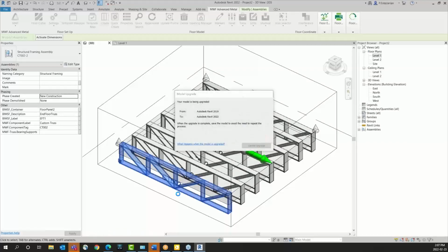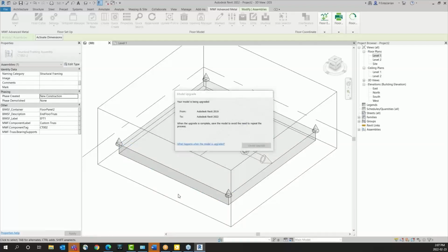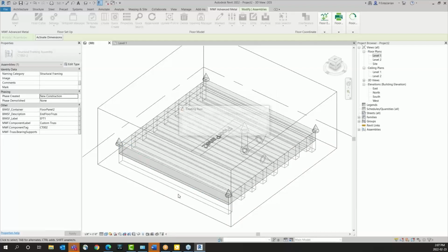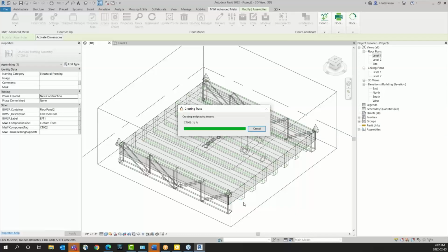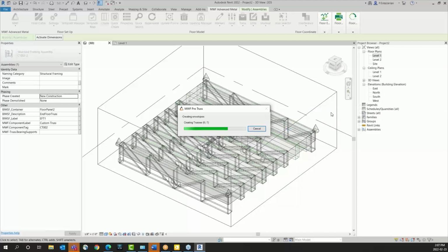We changed the settings for the joists in our floor panels, but as you might have seen, we have two different tabs. One for the end joists and the other one for other joists in our floor panel. Now we have changed the height of the heels of our joists. That is why if we take a look at it from the back view, it might take a few seconds because it's updating all the joists in our floor panel.